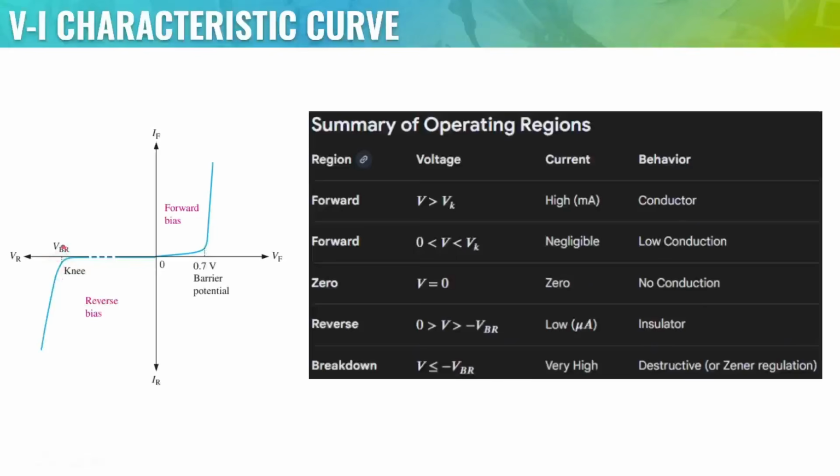And everything that goes past that, for example 1000 volts, can force the diode to conduct current in the wrong direction and maybe even permanently damage it. So if you've had a breadboard before, you know that the LEDs, or light emitting diodes, can be connected to other elements in the breadboard. If you use a battery that is too high for the LED and for the other parts like the wires, this one is going to fizzle out. So that's an example of reverse breakdown.